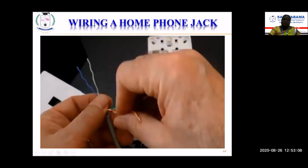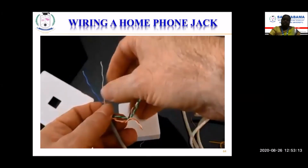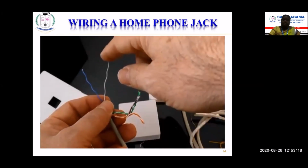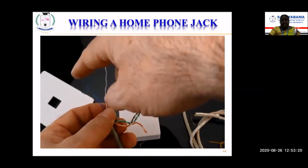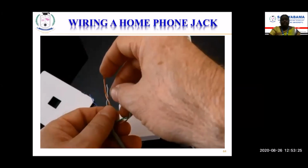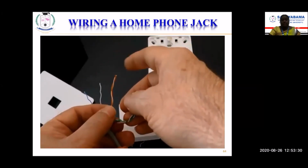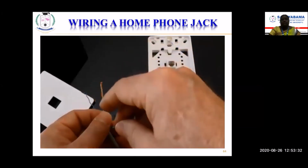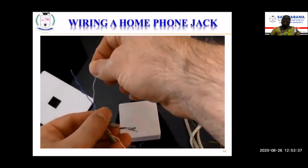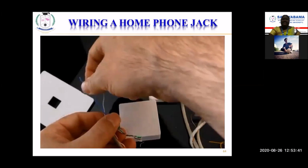Then what you want for line 1, if you just have one line in your home, or one phone number to your house, is the blue and the white. The white goes on the green post, the blue goes on the red post. And if you have 2 lines, then on the orange-white pair, the orange-white goes on the black, and the solid orange goes on the yellow. All right, so if you have this, all you're going to do is just match the blue-white pair, the white to the green, and then the blue to the red.